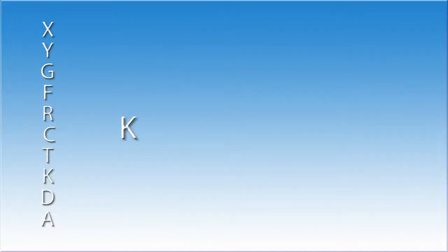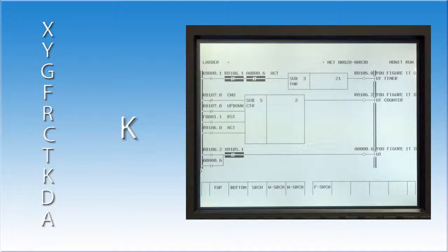The keep relays can also be used to enable or disable certain functions in a ladder logic, such as automatic doors, index tables, or robot interface. Typically, a machine tool builder will write one ladder for a machine model. Not all machines are sold with all options. The machine tool builder will use the keep relays to enable the options that a customer purchased.